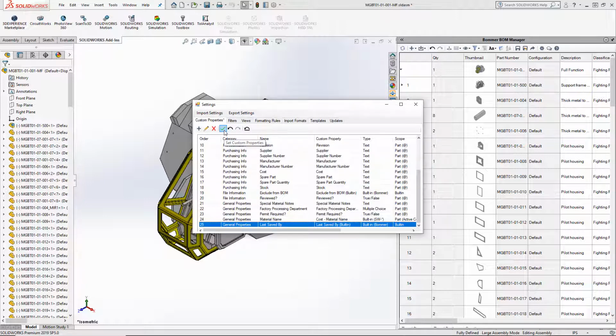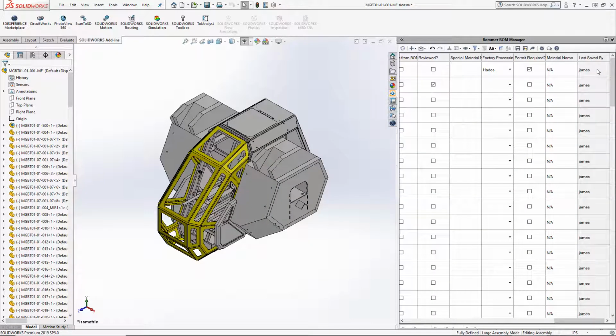After every configuration change, you will need to press the green check mark in the toolbar to save those changes. We'll press that button and then close this form, which will update that all properties view, and here it is, added to the end. If we wanted, we also could have changed the order of this property within the edit properties form.